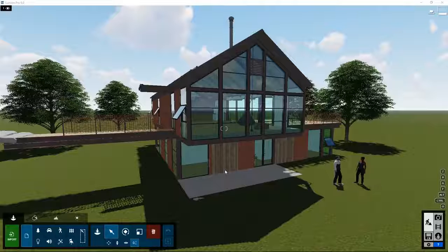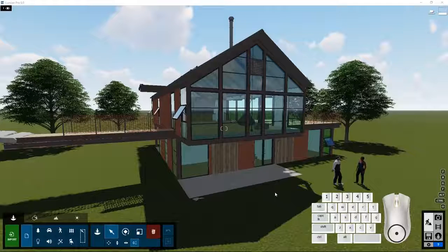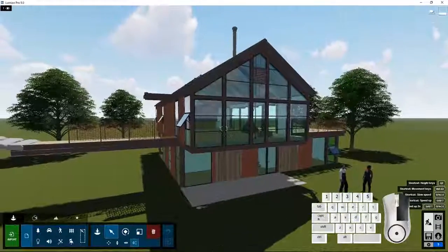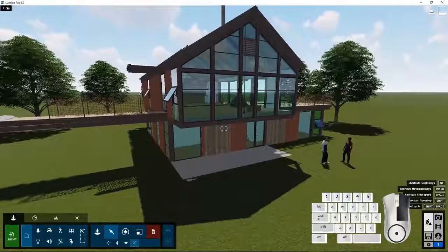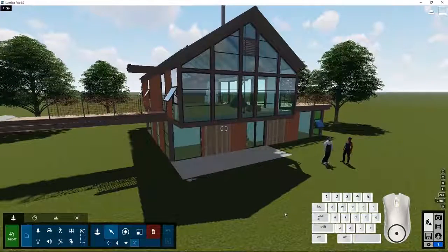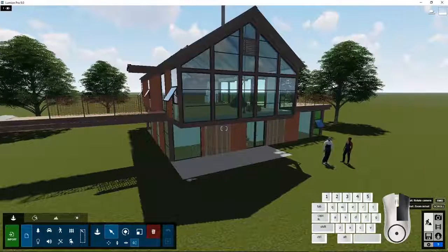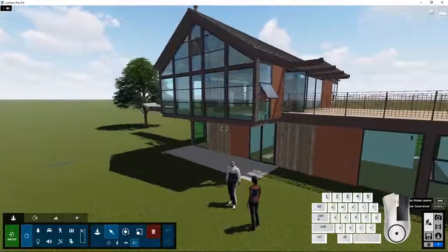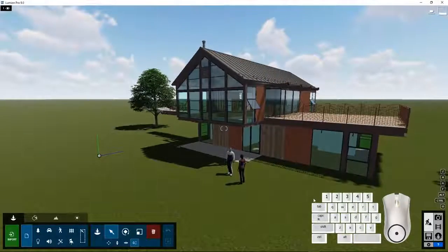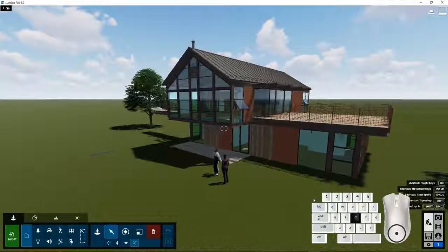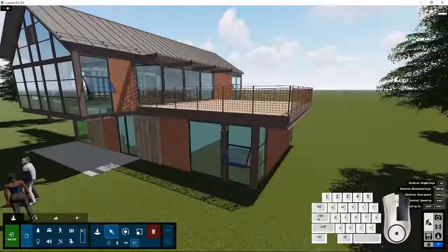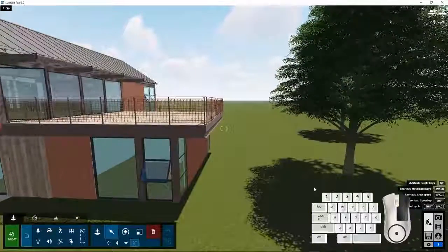I will temporarily show the overlay of the keyboard again. As we saw in Lesson 1, we can move around the scene in several ways. One of them is to move the center of the viewpoint in a certain direction. Press the O key, press the right mouse button, and we can circle around that point. You can scroll out. You can move left and right, forward, back, up and down with the Q, W, E, A, S, D keys. Scroll in and out. Rotate the viewpoint again. Scroll.